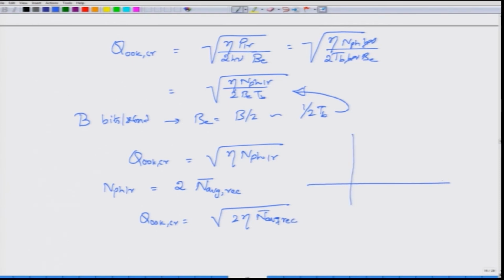If you quickly evaluate this, okay, you will see that the BER of course increases, but there is a 3 dB improvement between the direct detection receiver and the coherent receiver, which is operating under the shot noise limit, as the fiber length increases. You will also see that the length with the coherent receiver will be approximately twice the length with the direct detection receiver, and all this is happening because you are using this extra degree of freedom because of the coherent receiver. Okay, we will stop at this point and consider the limitations due to dispersion in the next module. Thank you very much.